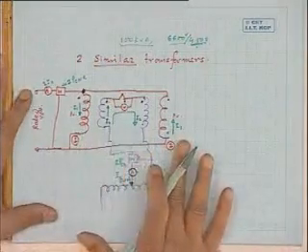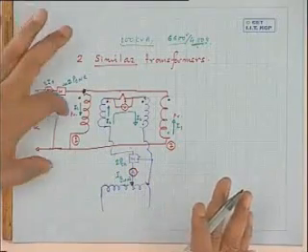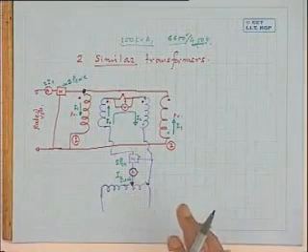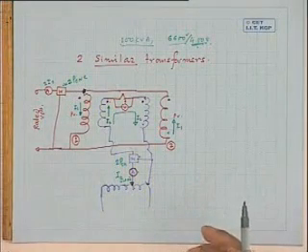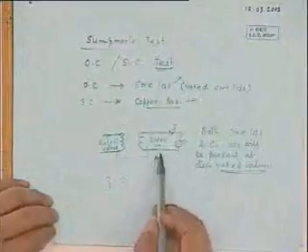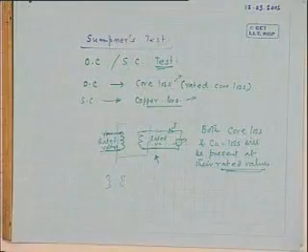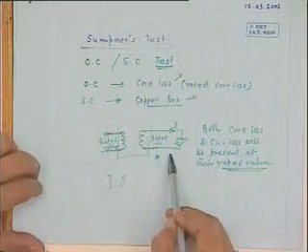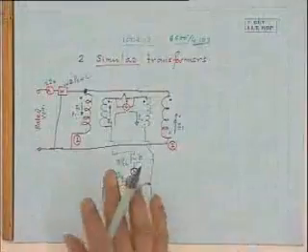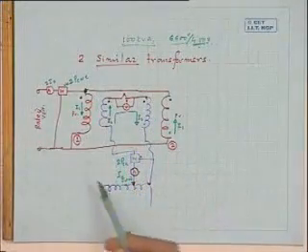Therefore, in this test, if you now look as an observer, what is happening? Both the transformers are having full load core losses because rated voltage has been applied. And at the same time, both the transformers are having full load copper losses. So as if this is the situation which you will get if you load the transformers separately with the appropriate load to fully load the transformers. Are you getting? But what is the advantage?